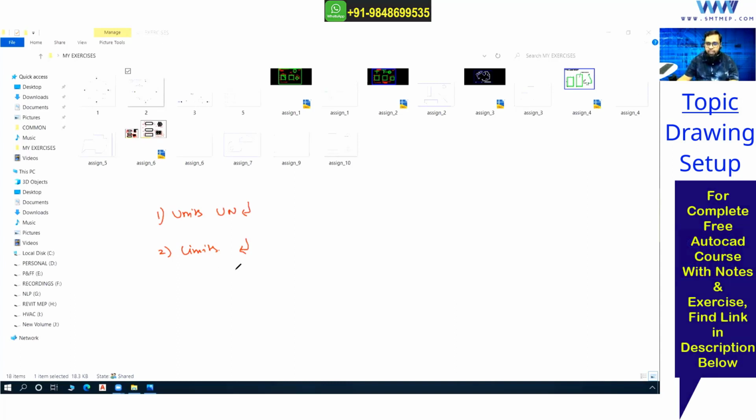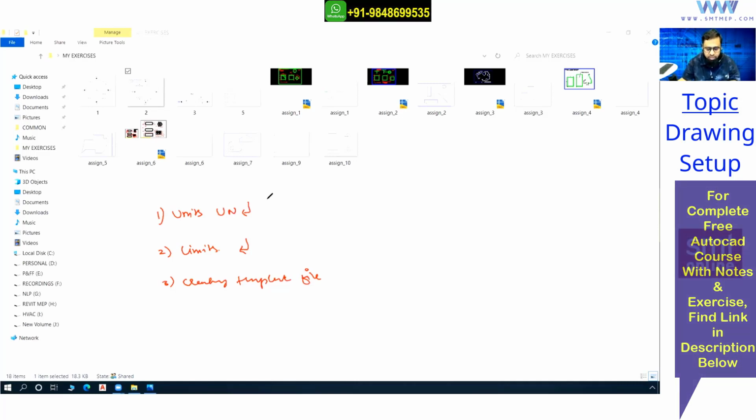If required, after setting the units and limits and some basic settings, we can save that as a template file. I'll show you that also. So that is creating a template file. Units is UN, limits is limits only. Then with the basic settings, we can create our own template file, and then we'll start the line command.